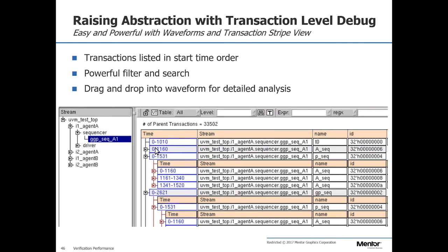There's a stream viewer within the Visualizer debugger, so I can look at what data packets have been sent through my design. It shows a stream of the packets that went through, what time they were generated, and what the different arguments on them were. You can trace by packet ID, and you can trace by a lot of different things.